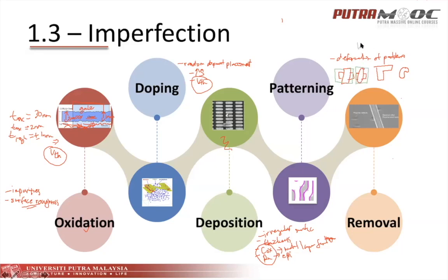It could affect your threshold voltage, and it could affect your high on and high off. If you are looking at the metal, this kind of pattern will introduce different R value, and perhaps C, and this could affect the delay in the circuit.